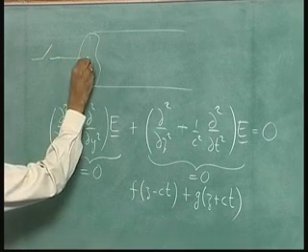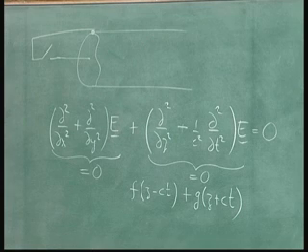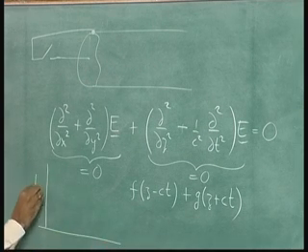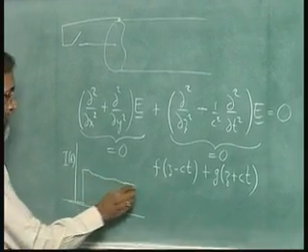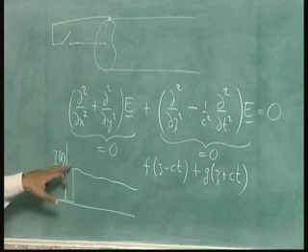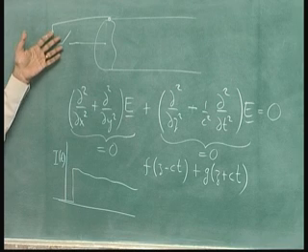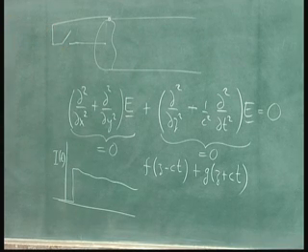One lead goes to the middle, the other lead goes to the outside conductor of my cable. When this switch closed, current went from 0 to some value and then continued to evolve. So there was a jump in current. This jump of course is limited by the inductance of the system here and parasitic capacitances and things like that.